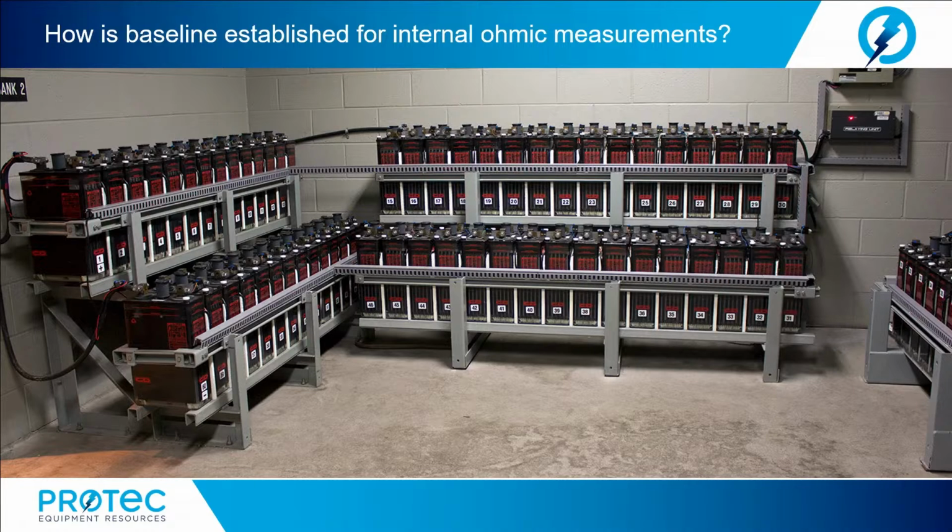Again, conductance readings from one manufacturer's test equipment do not correlate to impedance or possibly resistance readings from a different manufacturer's test equipment.